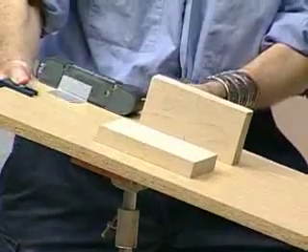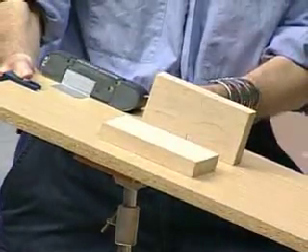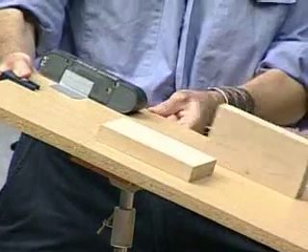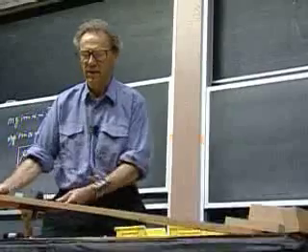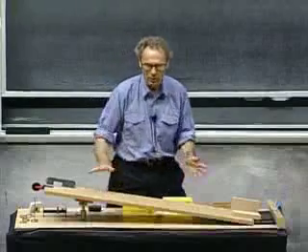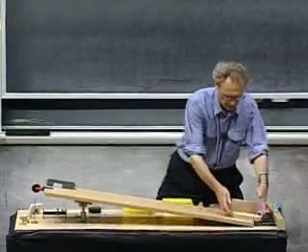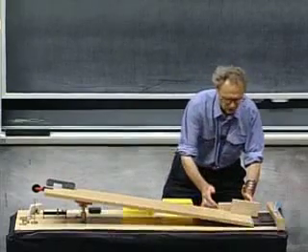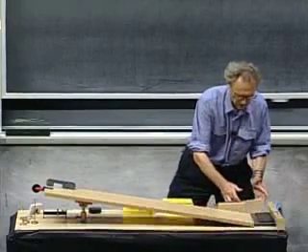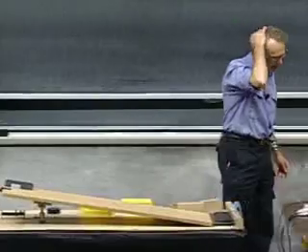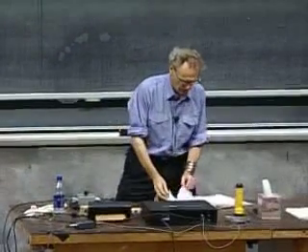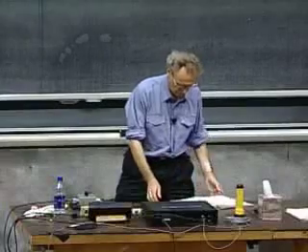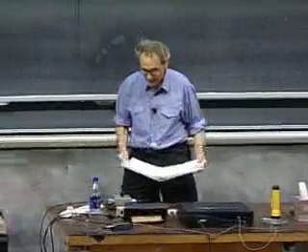14 degrees, 16, 18. One goes, and the other one follows, within 0.2 of a degree. And the reason why there's always some difference, of course, is that the plank is not exactly uniform. I have to be careful that I don't touch the critical surfaces. So you have seen difference in friction coefficients, and you have seen there's almost no effect of surface area, and there's no effect of the mass.